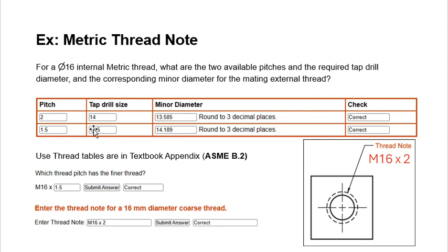Then go look for the diameter 16. That's your major diameter, given to you, 16 metric. So you will go into the M table, M16, and you will see the pitch is going to be 2. The tap drill size is going to be 14. It's in the table. As soon as you get there, you will find it. You're looking for the major diameter 16, which is M, because you're not in unified, you're in metric, so look for M16, and you will see all of that.